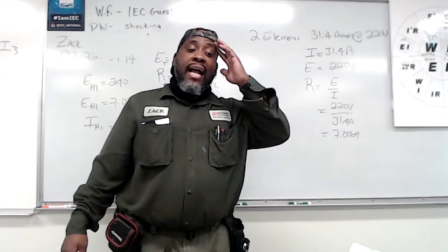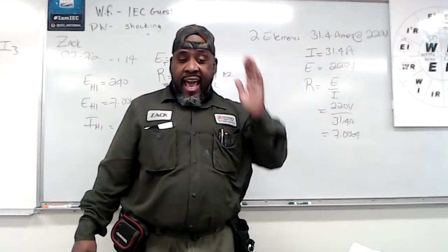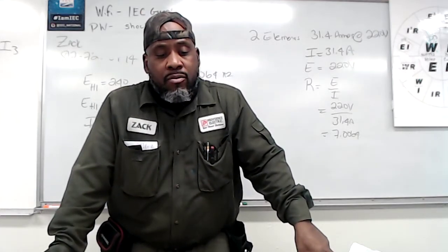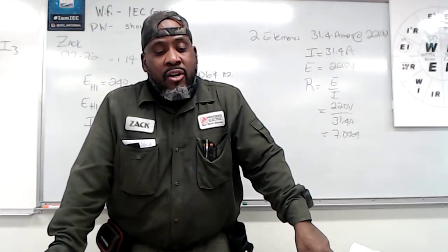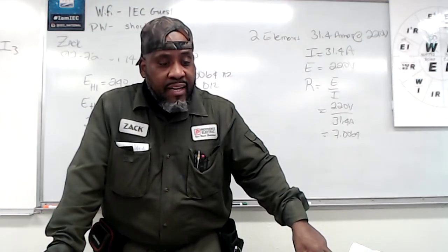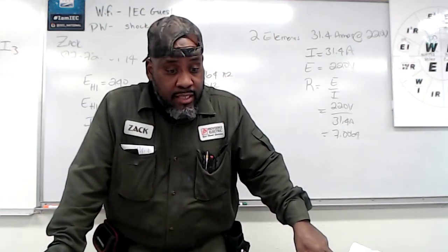So what I normally do is I just go with the first one. I need the left half of the receptacle to be connected to circuit 22 and switched with the left switch. So first of all, let's see if the left receptacle is connected to circuit 22. Is it?